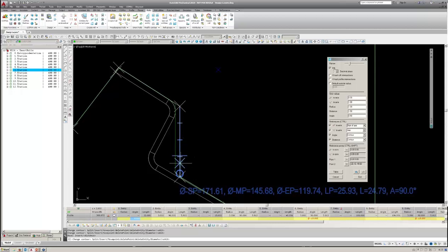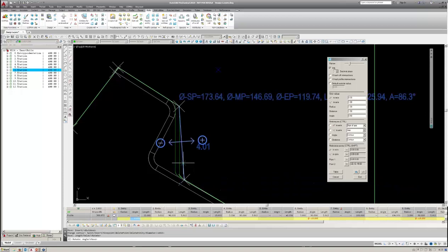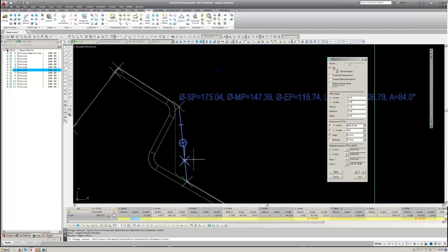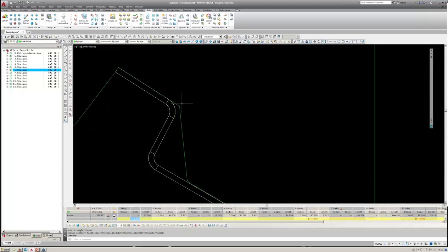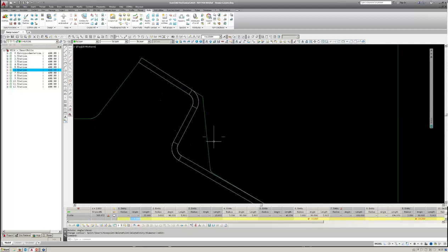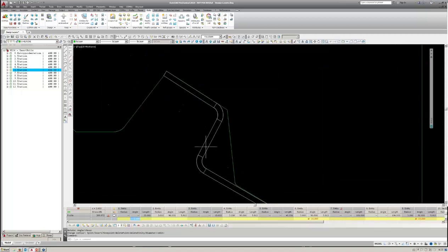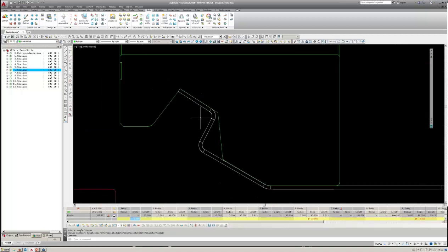And in that rotation, I'm going to pick in this position here and right click now, and then you can see my rotation here, and then hold down the control key, and I've got 0.5, so let's take 6 from there, and then right click. So you can see normally I'd have to draw lines, polylines, or modify entities to achieve that, and then reconstruct some radius on there. With the SmartRoll functionality, that's just done that in a few seconds. So again, saving lots of time in doing that.